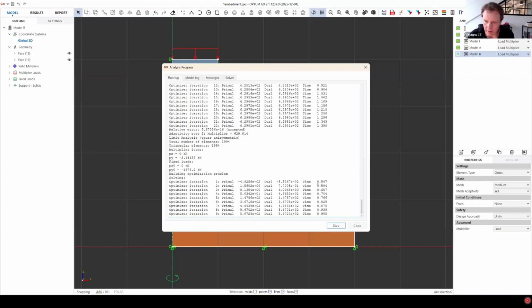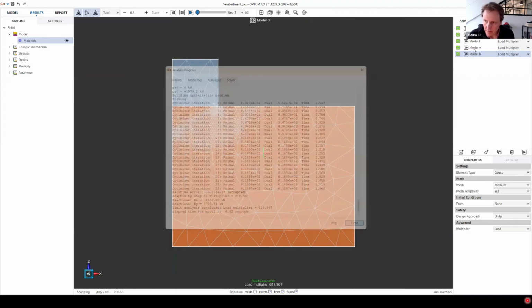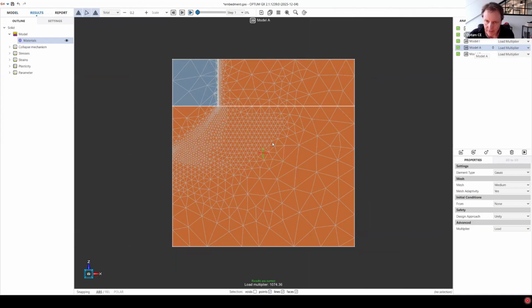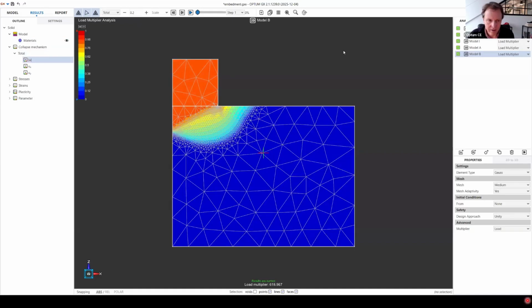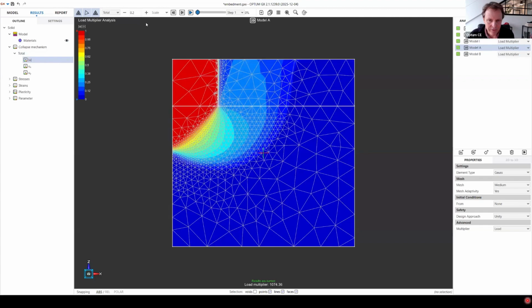And what happens is that, let's say the correct problem, or physically maybe correct problem, if you can trust this soil up here, you have a capacity of 1074, and then the approximate one, where you only include the weight of the soil, drops to 619. So almost a factor of 2 in this case, and that's of course because in order to fail, the soil has to fail up through this soil here.